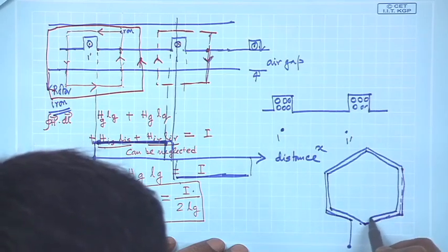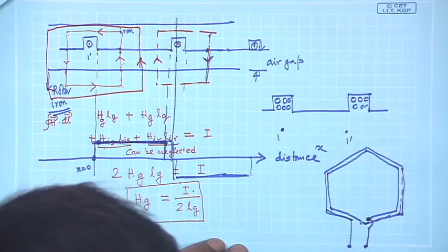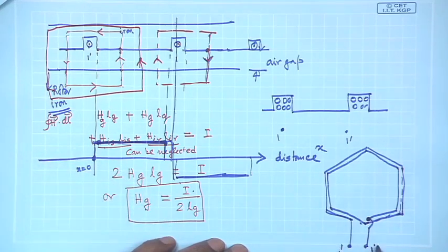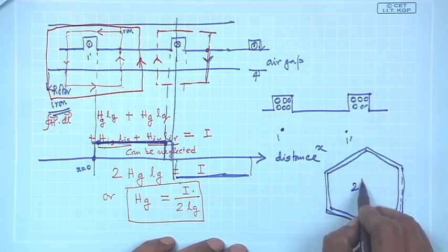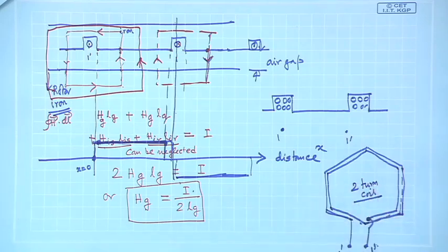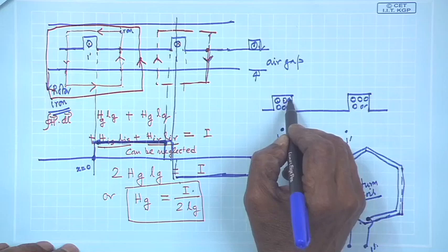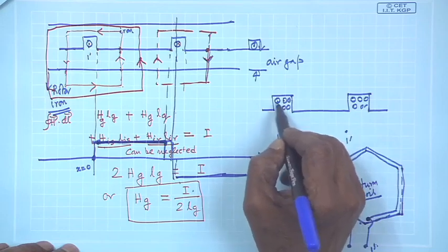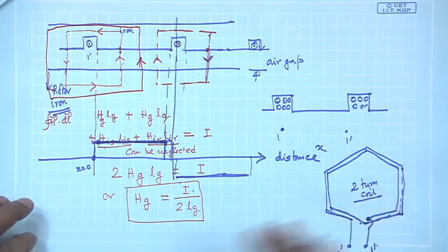Come out here, and suppose I stop here. So, this will be my 1 dash to 1. So, it will be a two turn coil. In fact, in machines multi-turn coils are used, because BLV is the voltage, and when these things move in B, all these conductors will have BLV and they will be added up. So, large voltage you can get. Therefore, it is a multi-turn coil.